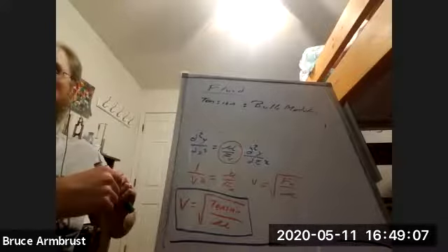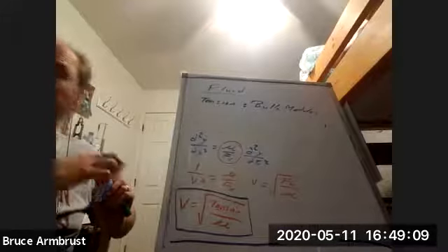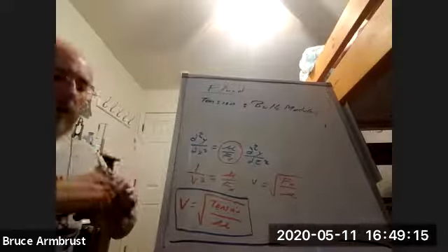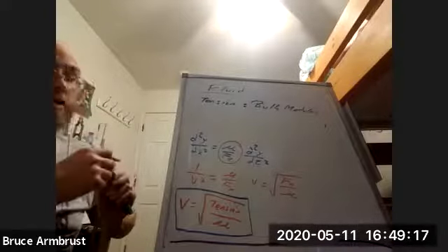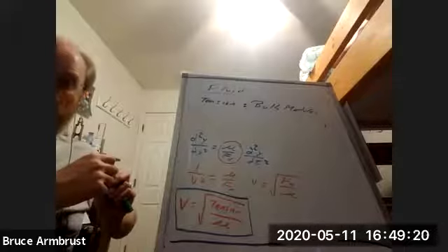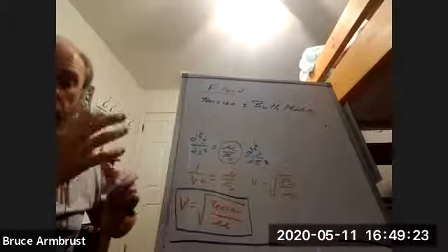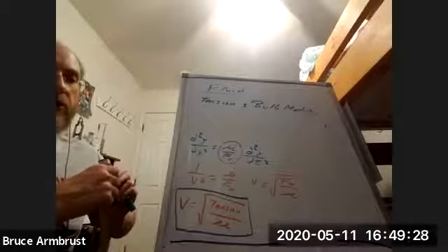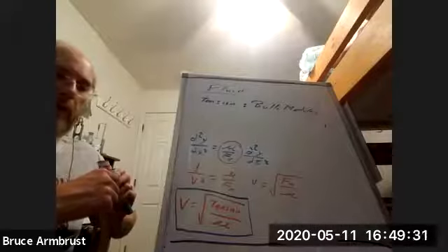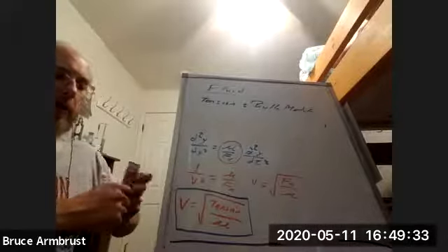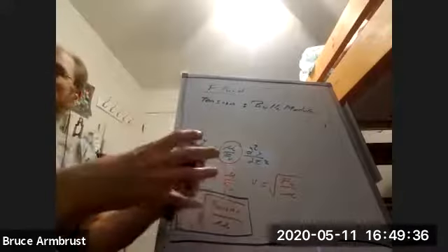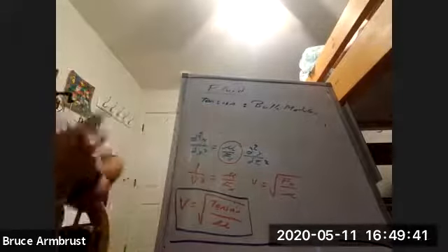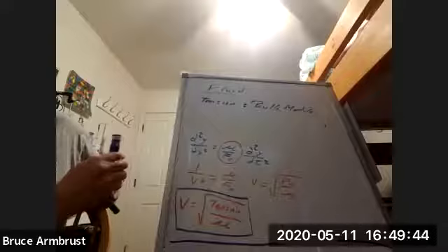So hopefully you remember modulus. It's a ratio of stress versus strain. So we're really looking at force being applied versus actual change in the material. And so bulk modulus with a fluid is pressure per surface area. And then the strain is actually the change in volume, right? Because think about that styrofoam cup. There was great pressure pushing from the outside, and it caused it to shrink in volume. Okay, so the role of tension is going to be played by the bulk modulus.